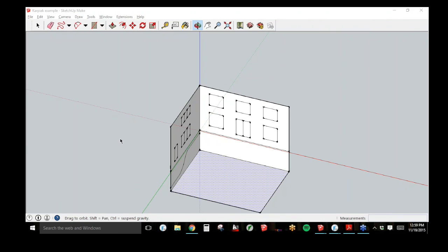Okay. And the last question is, exterior dimension of the window accounting for over insulation, so exposed window dimensions? No. It's the actual window dimensions. So if you have a 4x6 window, you input 4 feet in one direction, 6 feet in the other direction. The over insulation gets accounted for only in the side installation value or the corner bridge value for the window installation. And it also gets accounted for in the reveal shading, so the shading from the window being inset in the wall.